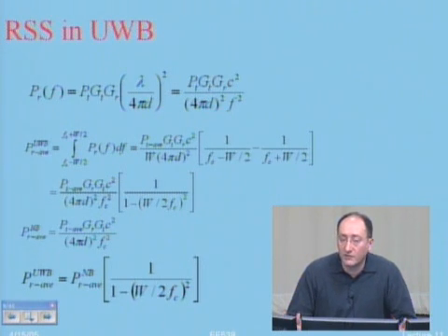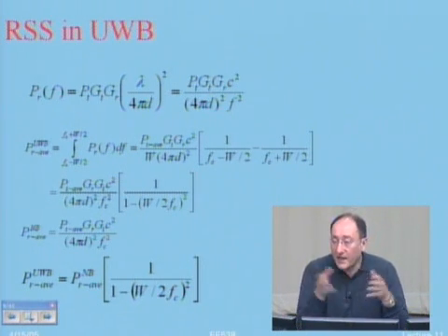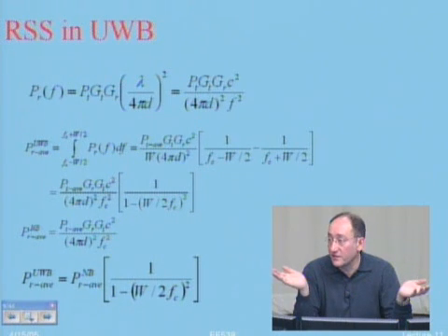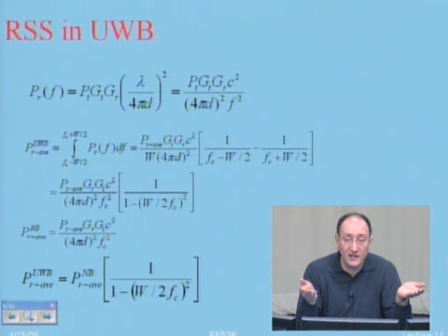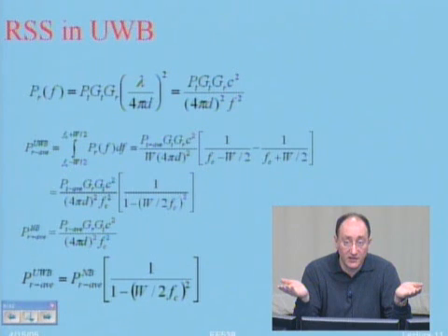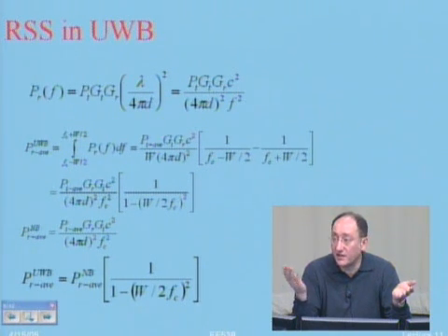What is the meaning of ultra-wideband? It means that my bandwidth is over 1 gigahertz. If you want to compare with TDMA systems, the bandwidth is 200 kilohertz. That's GSM. IS-95 is 1.25 megahertz. And if you go to wideband CDMA, it is 5 megahertz.